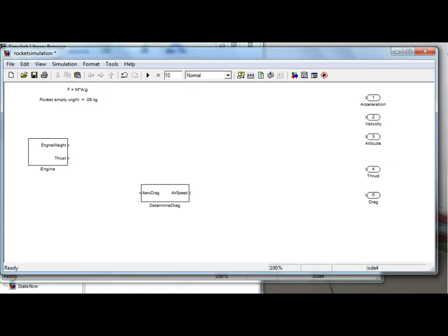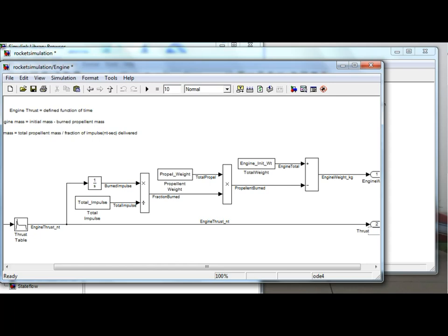And if I go up to the next level, I see I have this thrust output here, and I'm going to grab on that output and just drag it out into space a little bit. And if I double-click on the signal itself, right on the signal, it creates a signal label, and if I put angle brackets like that, it's going to essentially propagate the signal from below. And because I've labeled the output and I've labeled the signal, and I see that they match, I have some confidence that I didn't miswire things underneath there, which is really easy to do.